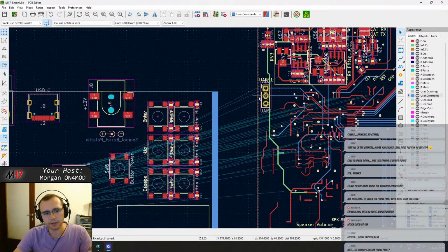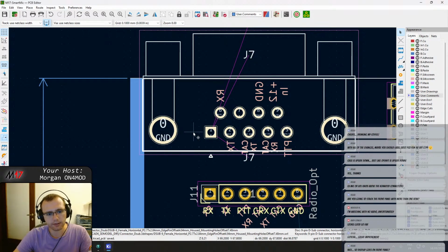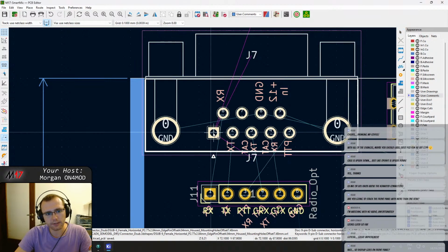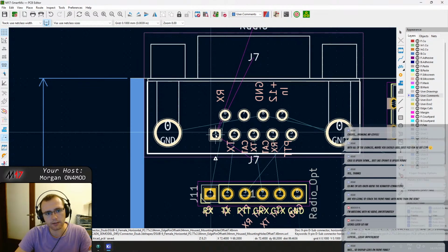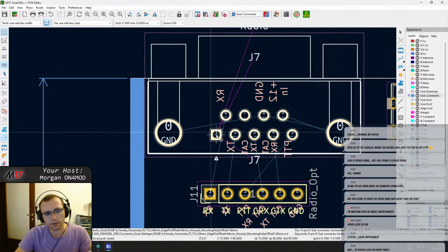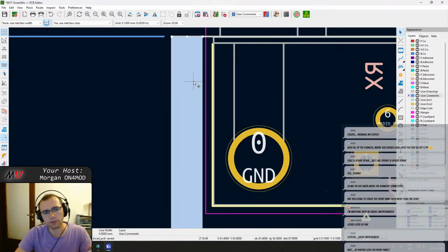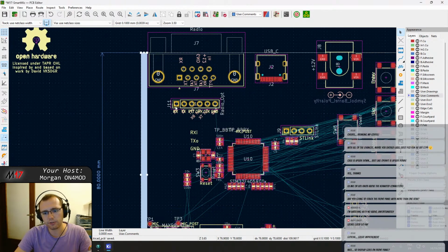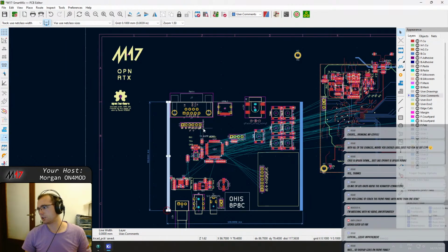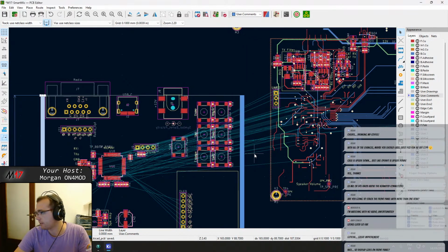Yeah, okay. I wanted to do the connectors. Okay, so this does need to move on the side because it's colliding. Okay, so they have like a bit of clearance. So as a reminder, those are the 2mm that are gonna form the rails, which are gonna be used to slide the board in the enclosure on each side. We have 2 millimeters of clearance.